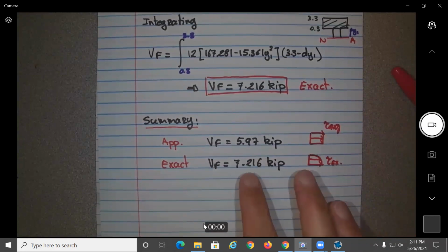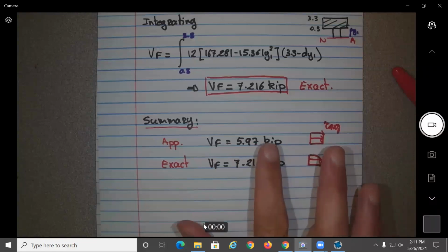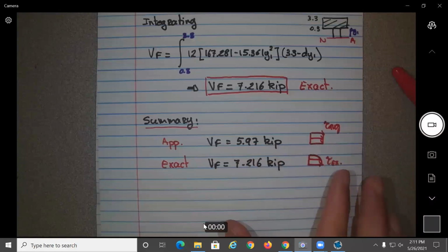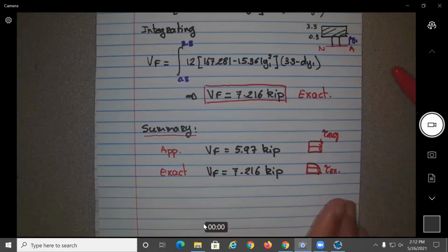But obviously, in order to find this one, what happens is a lot more calculations, no? And you need to do the integral. But the reason I cover this again is that if you do designs, you need to be aware that if you're taking the average of stresses, you might not be able to capture the maximum value. I'm going to tell you right now, 99% of the time, people do hand calculations for shear.